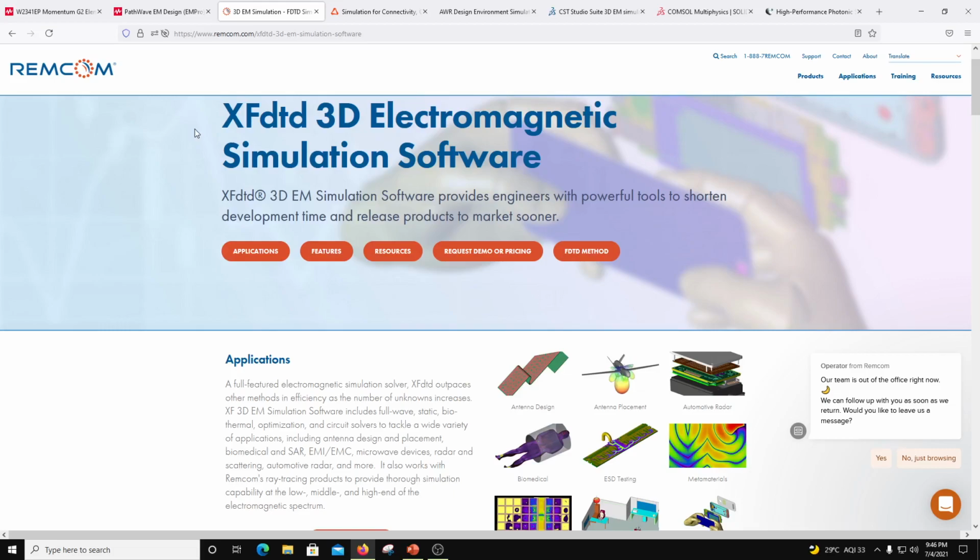Now in FDTD, another thing which they do is what is called absorbing boundary conditions, right? So you do an absolute absorption. This is more like an anechoic chamber, like when you test an antenna in an anechoic chamber, whatever is thrown at the walls of the chamber is all absorbed by the cone structure, which is coated with some kind of dielectric material to absorb everything which is thrown at it.